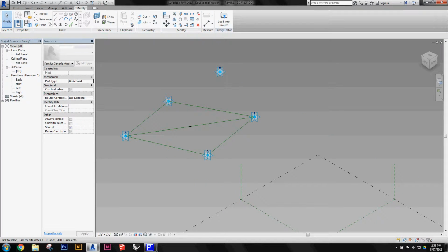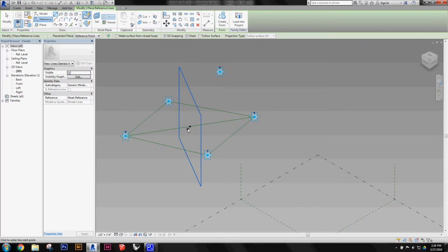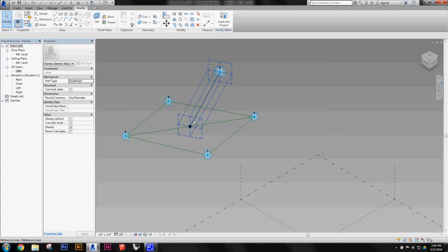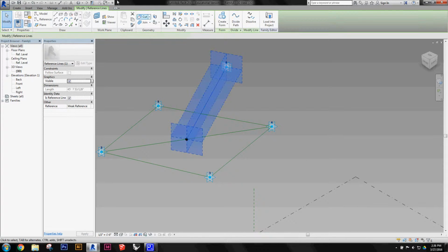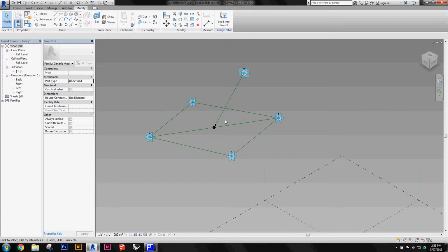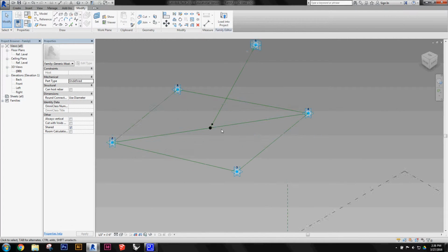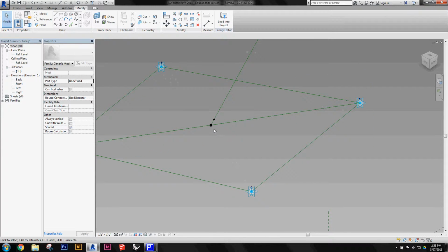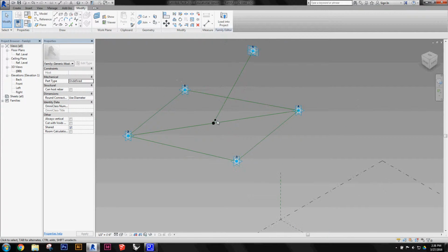And so the next thing is to use the number 5 adaptive point to control the direction. So basically we'll have the reference lines first, and set a point on that. The next step is that I'm trying to make the length of this line the same as this line. So first we'll get a parameter to record the length of the line from point 2 to point 4.